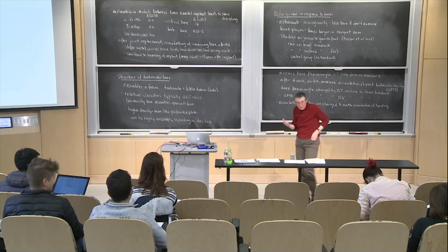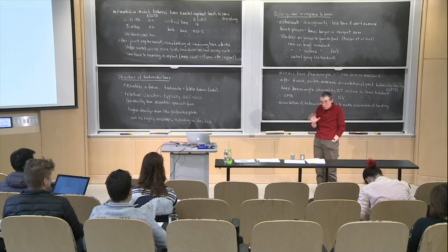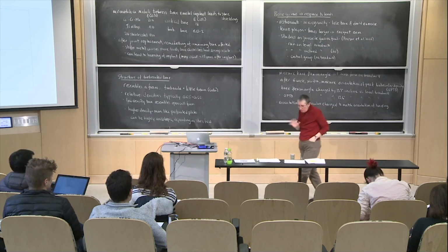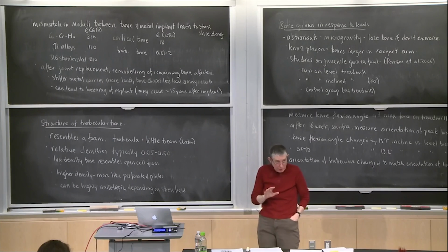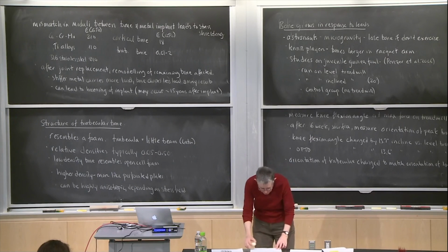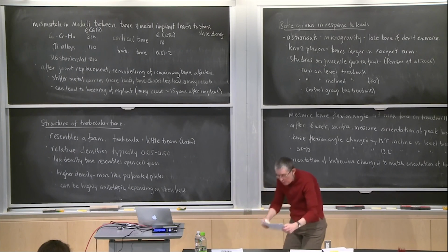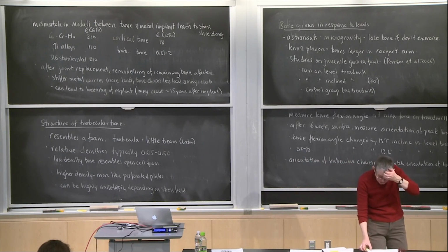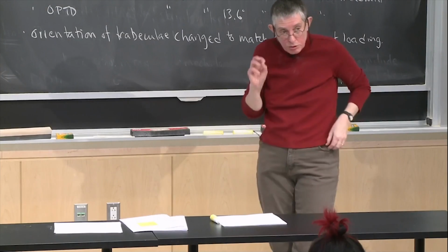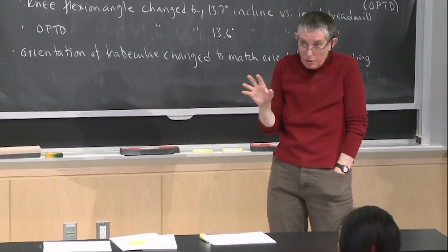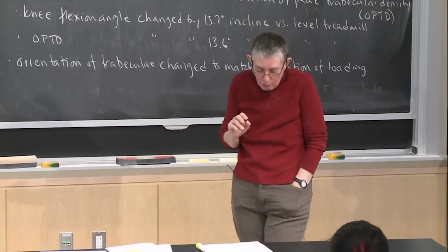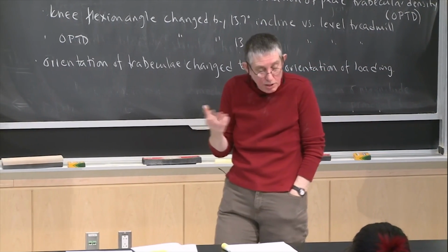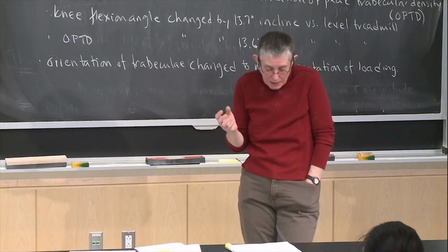Okay, so if we want to use the models for foams to try to describe the trabecular bone, we need to know something about the properties of the solid. Remember, we used the properties of the solid in the models. So we want to get the properties of the solid in the trabeculae, and there are a couple of ways you can do this. To get the moduli, you can use an ultrasonic wave propagation method, and you can measure a modulus that way. If they do that, they measure a modulus between about 15 and 18 gigapascals.